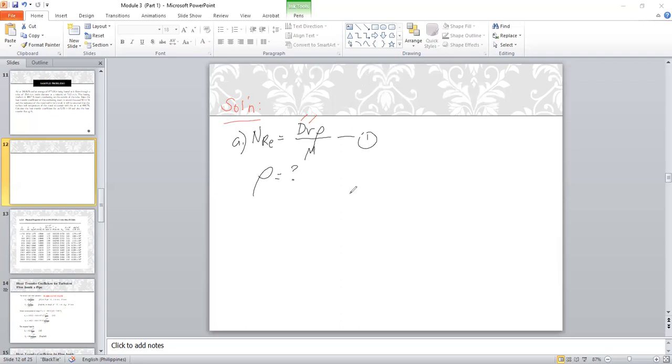The ideal gas law, mates. Okay, thank you for that. Very good. So you need to assume ideal behavior. And if you assume ideal behavior, we go back to the ideal gas law equation, PV equals nRT. And from the n here, you can write mass over molecular weight, and you still have RT here.